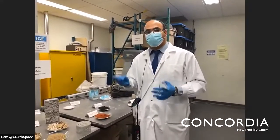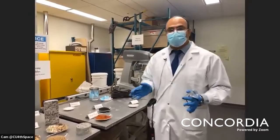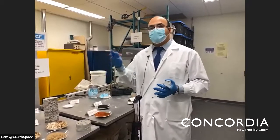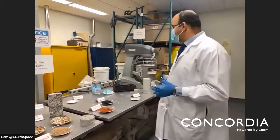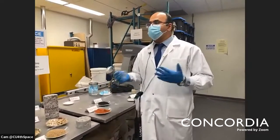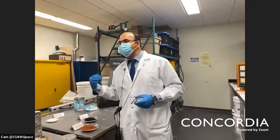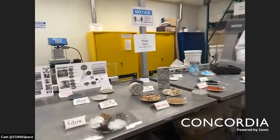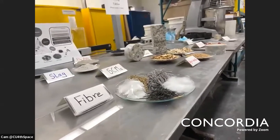You have to characterize your material. So after we get our material, we start making physical and chemical characterization. We may do X-ray and scanning electron microscope to look at the microstructure. Then we select the application which suits it most. Then we make trial samples, expose them to different environments, and see the performance of our material. Is it going to work in a harsh environment like winter, or do we need to go back to the design stage and make some modification by adding fiber, cementitious material, or new admixtures, until we reach the point where we have a product that can survive outside?